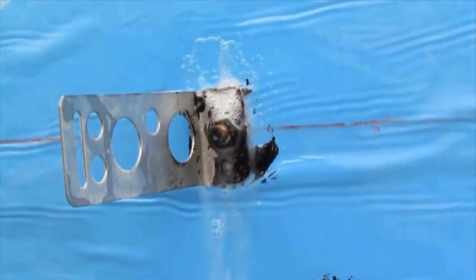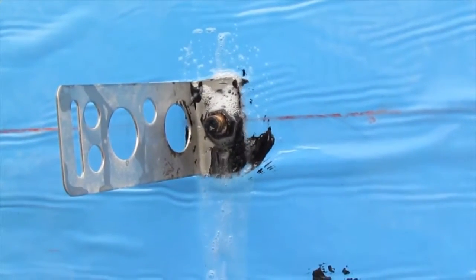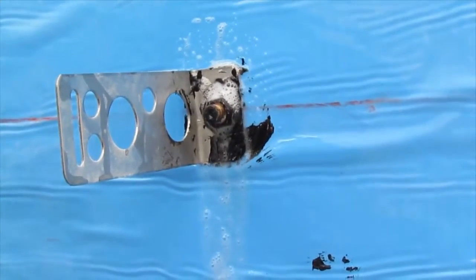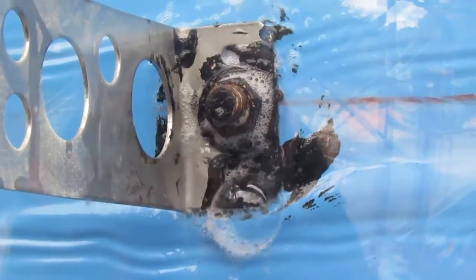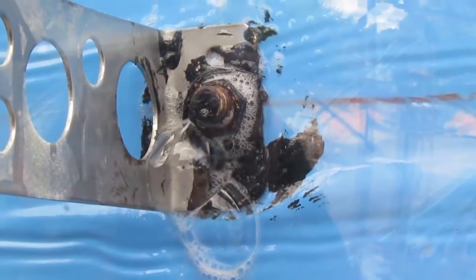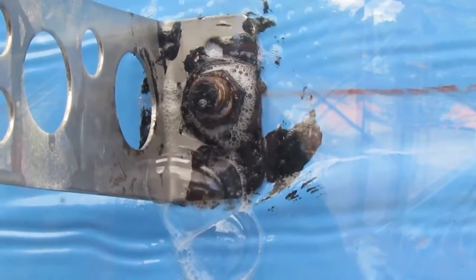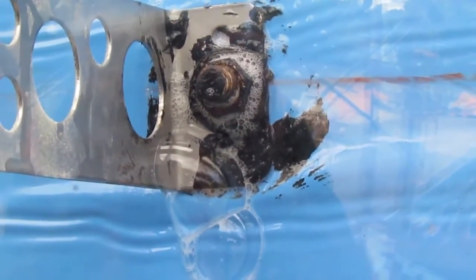The bubbles here show a leak. In order to use the detector, a surfactant is first applied to the area being tested. A dome is placed over it and a pressure differential is created, drawing air through the leak or deficiency to show the bubbles form as you see here.